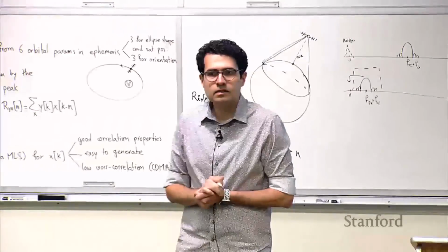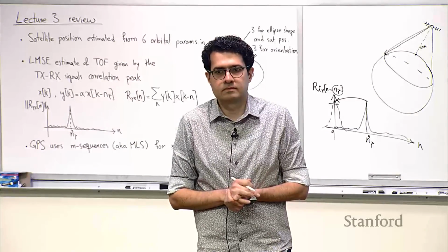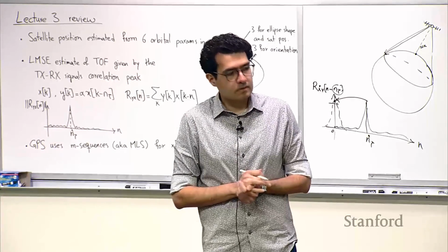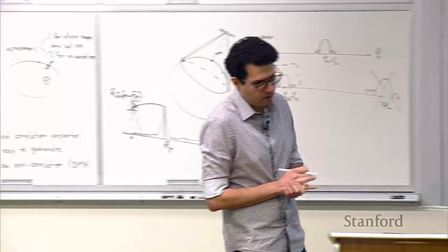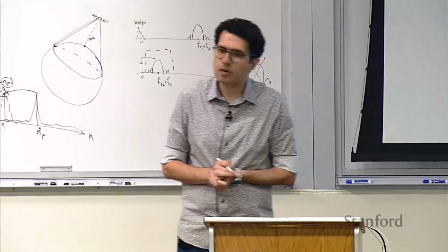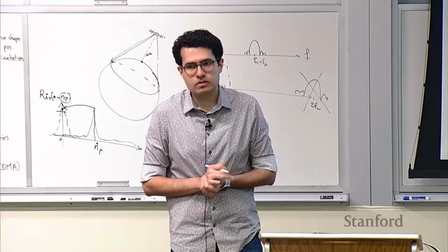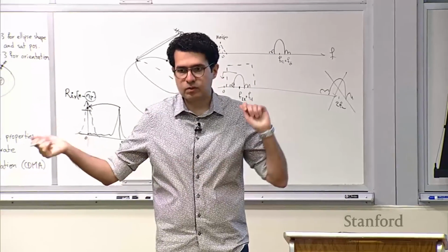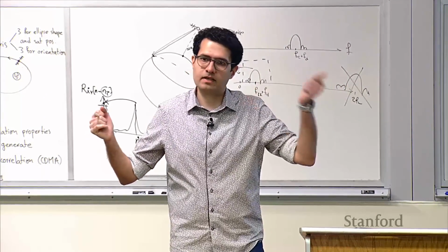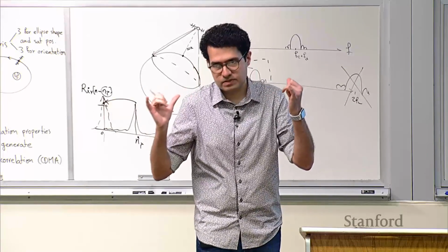For the atmospheric delays, why can't the GPS use a simple atmospheric model? Great question. So the question is, for the atmospheric delays, why can't the receiver use some model to compensate? And the more sophisticated ones do. The way the models work is that the delays are frequency dependent. So if you acquire signals from two separate channels, say L1 and L2 or L1 and L5, you can use that extra piece of information.